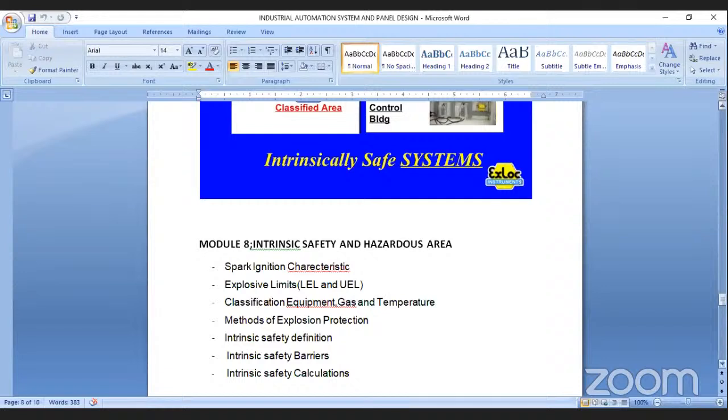We'll discuss both and try to correlate them, because as a designer or in material procurement, you will get vendors from European or American sides. You will have both, and you have to be able to compare these two things. So those hazardous areas we'll discuss, and when it comes to zone 0 systems, you need an intrinsic safety philosophy. What are intrinsically safe systems? That is important.